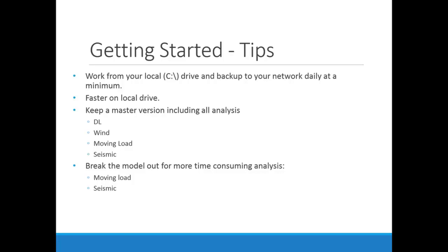Another thing, this might not be true for you, but it's certainly true for me: I find that my model will run many times faster from my local C drive than from a network drive or even my external hard drive. So give that a try. But always remember to back up to your network drive, to your project folder, on a regular basis, because you don't want stuff stuck on your hard drive and then have your hard drive crash.